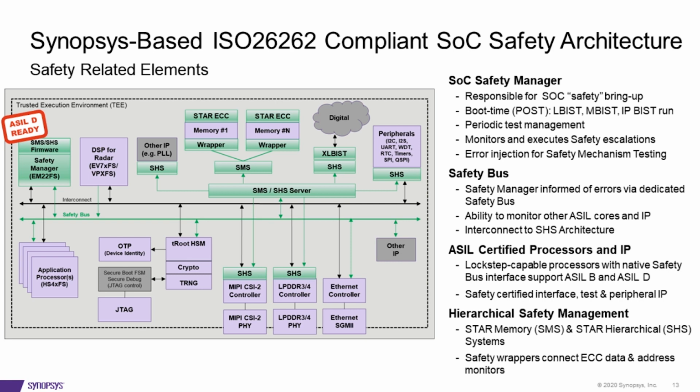And so, to minimize the amount of extra work a customer might have to do to get their existing IP, especially IP that may come from, say, a consumer-based device, and they want to move that IP when they create a safety automotive device, they can still use that IP. They tie that off with the SMS or SHS logic, and then it can tie into the overall safety architecture. But independent of whether or not the architecture uses Synopsys IP, the concept of memory BIST and logic BIST being tied into a top-level safety manager is a very common architecture that we're seeing more and more in the market.